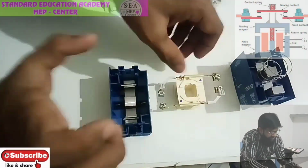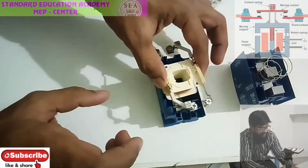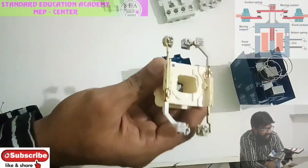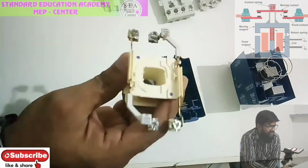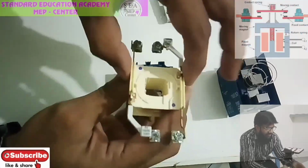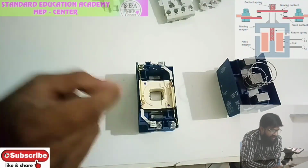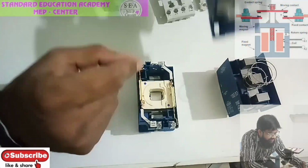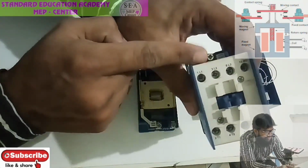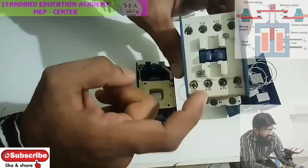I have just opened this contactor. Actually, the contactor will be like this. It has a coil, which plays a very important role in contactor working. The coil will usually be placed over here like this. If the coil is energized, then only supply goes from the source to the load, that is from L1, L2, L3 to T1, T2, T3.